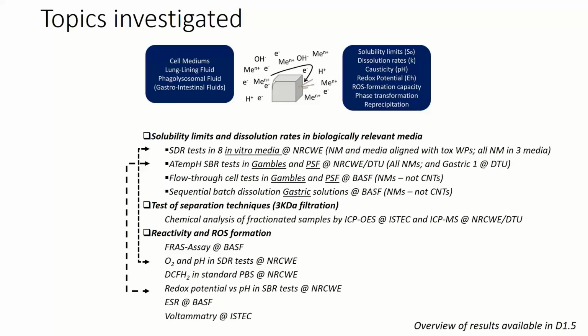We developed an atmosphere, temperature and pH controlled stirred batch reactor system in which we tested the solubility and reactivity as well as the dissolution rates in Gamble's and phagolysosomal fluids. And here we tested all nanomaterials, and one experiment was also conducted at DTU as part of the PhD project with Elsa Holmfred there, looking into the dissolution of cerium oxide.